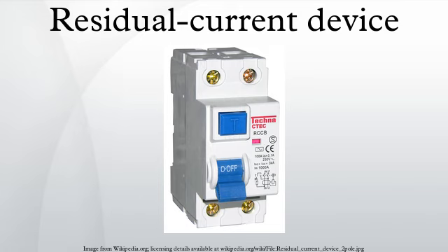In North America, GFI receptacles can be used in cases where there is no grounding conductor, but must be labeled as ungrounded. An ungrounded GFI receptacle will trip using the built-in test button, but will not trip using a GFI test plug, because the plug tests by shorting a small current from line to the non-existent ground. Electrical sockets with included RCDs are becoming common.